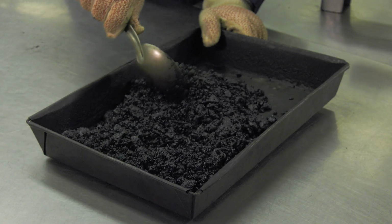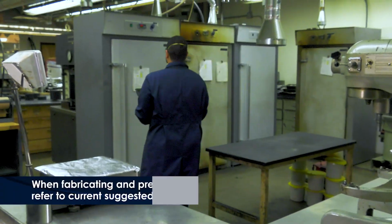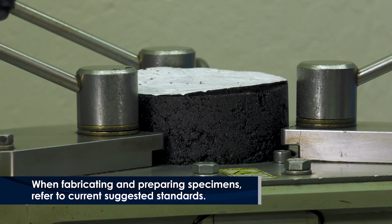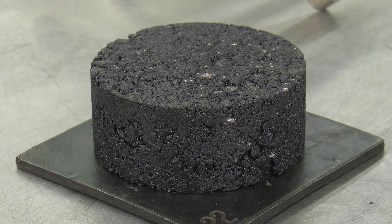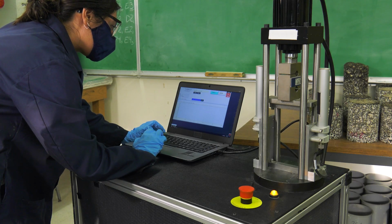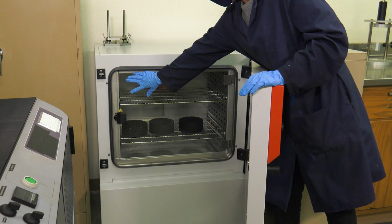For laboratory-prepared specimens, short-term condition the asphalt mixture according to AASHTO R30 and fabricate 3 150 mm diameter specimens at the target air void and target height using a Superpave gyratory compactor, or SGC. Allow the specimens to cool. Determine the test temperature based on the climatic intermediate performance grade temperature as described in the standard.